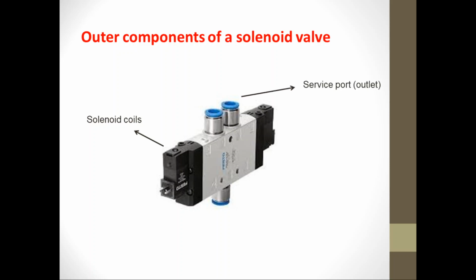The service ports, or the outlets, are the ports that are connected to the pneumatic cylinder. Depending on the type of solenoid valve, the number of service ports will also vary. We will discuss more of that in the upcoming slides.